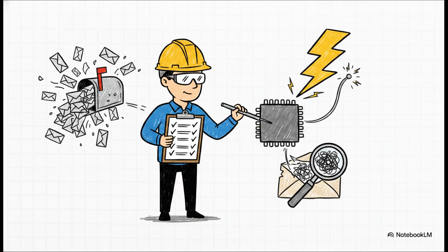They'll actively inject parity errors to see if the hardware actually catches them. They'll completely flood the RX FIFO to ensure it triggers an overflow alert gracefully rather than just crashing. And they validate that every single hardware interrupt fires exactly when it's supposed to. They have to ensure that UART can handle the messy, error-prone real world of flipped bits and mismatched timings.